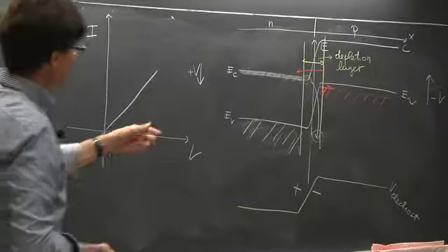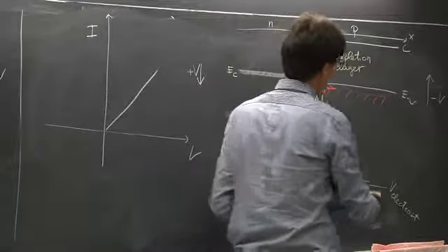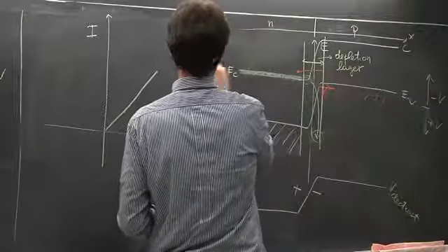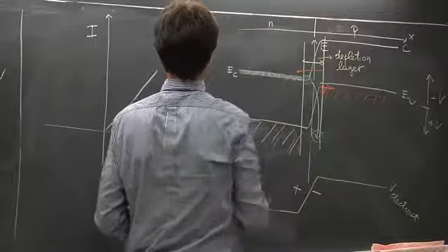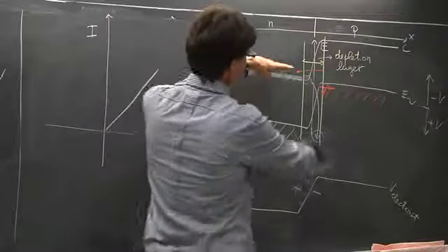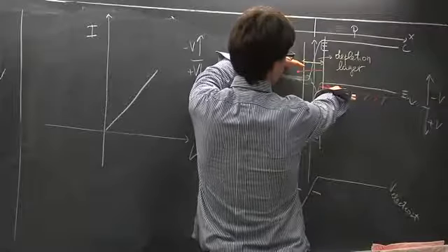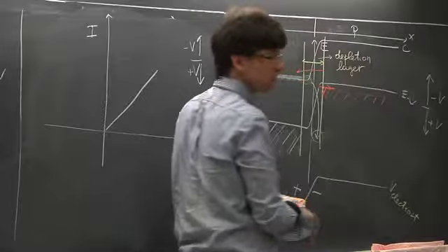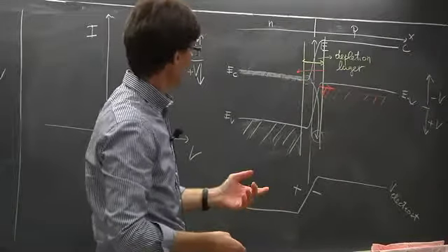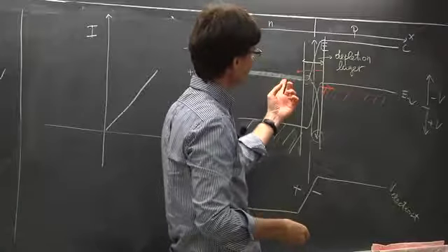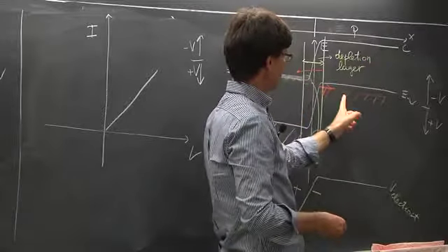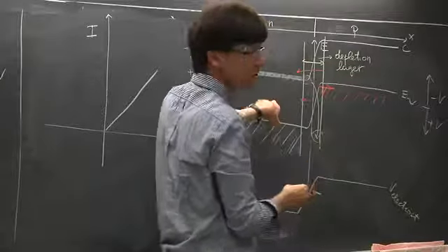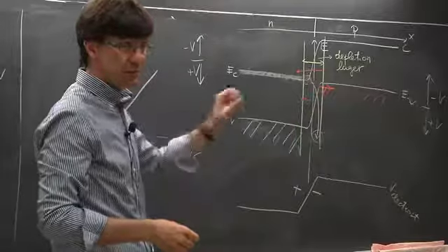The interesting part is the other one. It's when I lower here the potential, so apply a positive bias here and a negative bias here. Because if I do this, I'm lifting this band with respect to this one, right? And you see there's no chance for electrons to flow any longer, because I have a very small amount of electrons here. These electrons here, they won't be able to flow any longer because there are no available states on the left side to flow into.